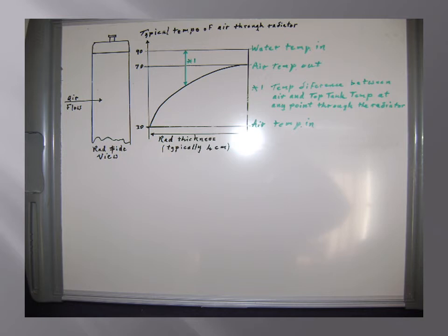In other words, we are dealing here with the law of diminishing returns, which begs the question: must you use a 2-core radiator or a 3-core radiator? The answer is a 3-core radiator might have more fins to transfer the heat, but a 2-core radiator may have less resistance to the airflow. So the answer is you simply have to do a test.